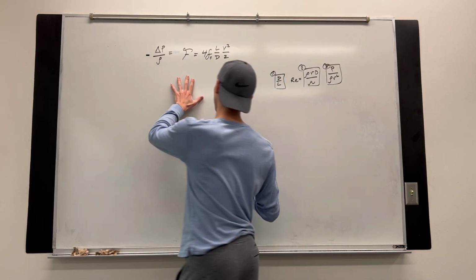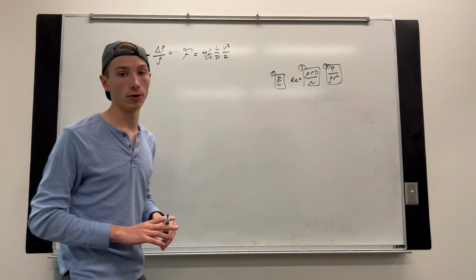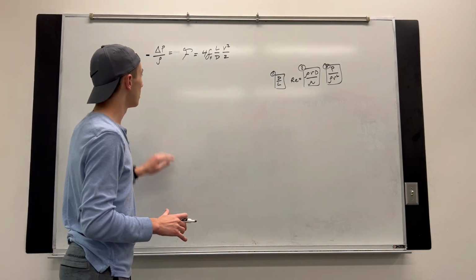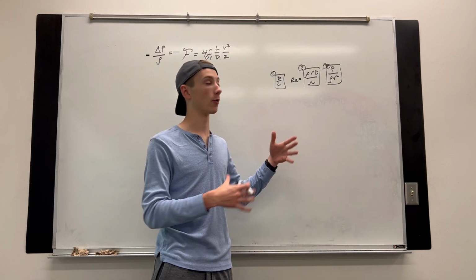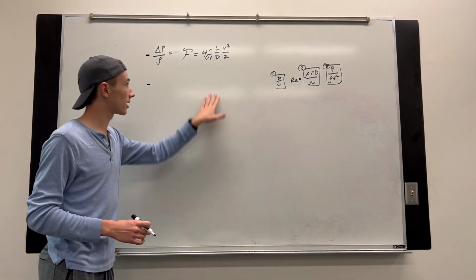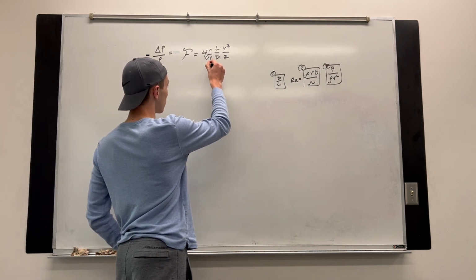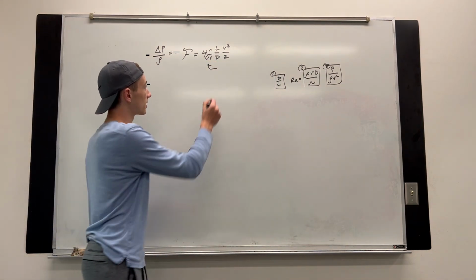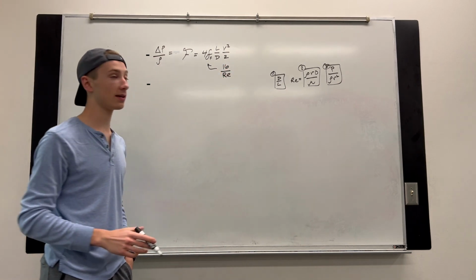So I've rewritten down our Bernoulli's equation here, and then our 3 dimensionless groups that we've just come up with. And remember, we're trying to show that this equation is just a combination of these dimensionless groups that I've worked out, right? Okay, so let's talk about this friction factor. So the friction factor is equal to 16 over the Reynolds number, and this is the fanning friction factor.